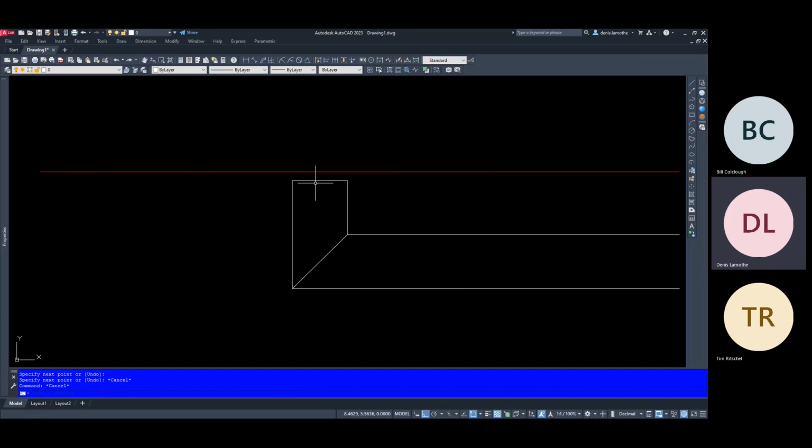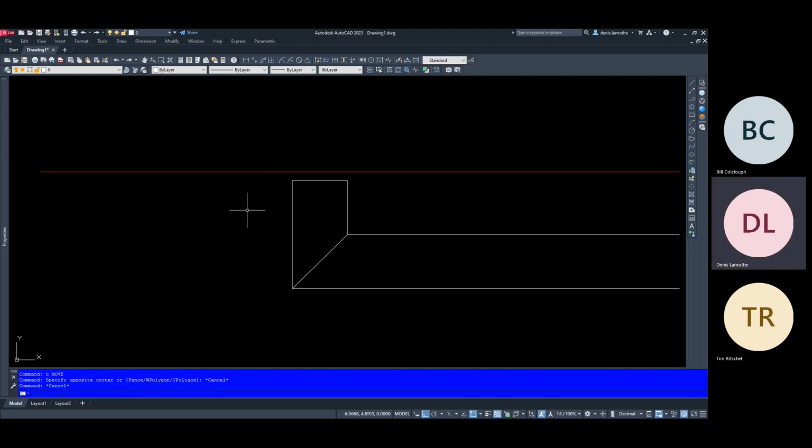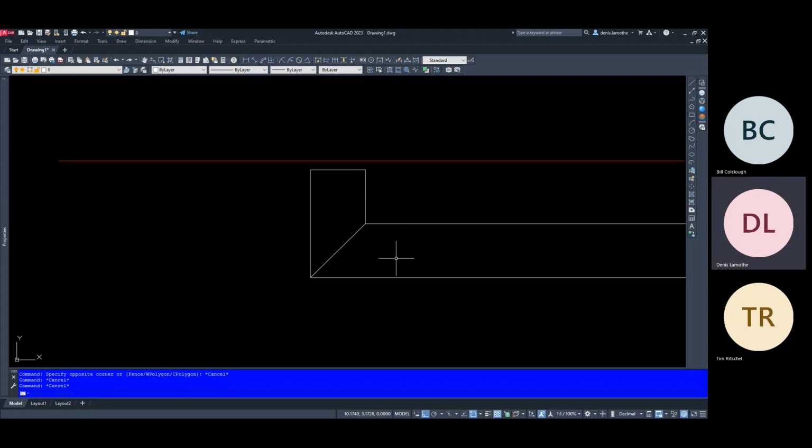We wouldn't want that inconsistency, the far point, interfering with our handrail if we were to design it flush with the wall. So we're going to usually draw it about 1/4 inch away from the wall, so that we don't have any conflicts with the structure when we show up with our finished handrail and install it on the site. So that's generally what I mean with the handrail return to the wall.